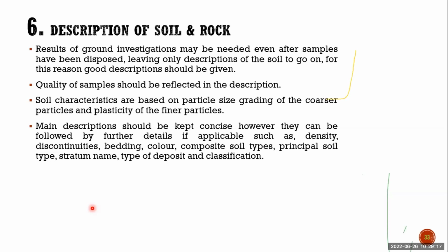That is very important. As per the different standards, mostly all are the same, with little variation. In general, you will give the density properties of the soil, like consistency, very soft, or dense, very dense, this kind of characteristics. Then the color of the sample, and the plasticity characteristics of the sample. If it is from the trial pit, we will know the moisture content, like slightly moist or dry. Then what is the main soil type? Along with the soil type, is there any other fraction like gravels or boulders? And what is the origin?